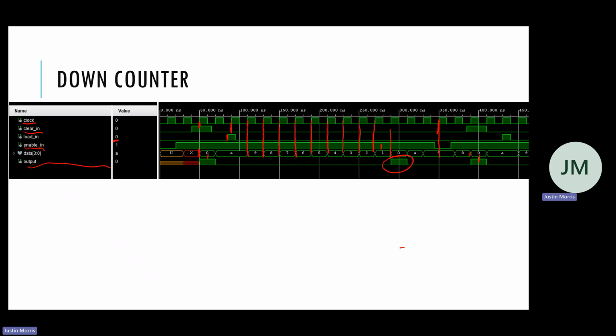But going back to our previous slides, with the finite state machine, you have combinational logic block C1 to handle what is the next state. And then you have combinational logic block C2, which handles the outputs, right? So it can be useful to separate these two things.